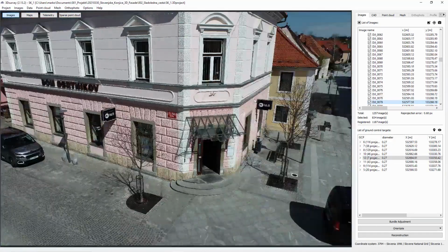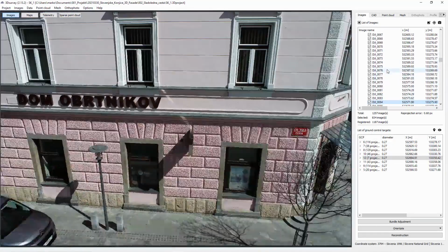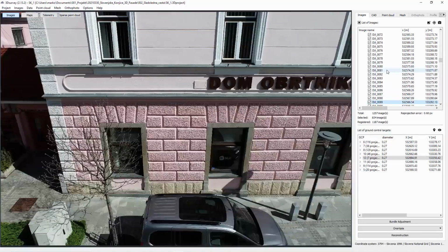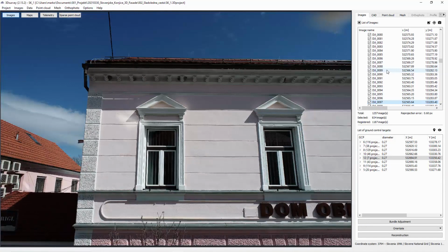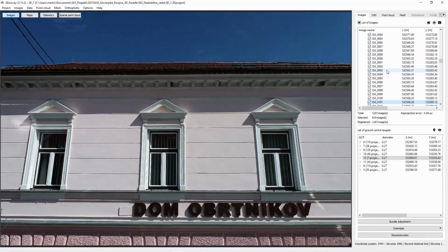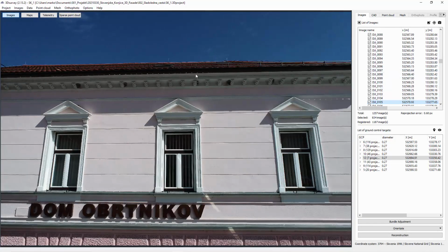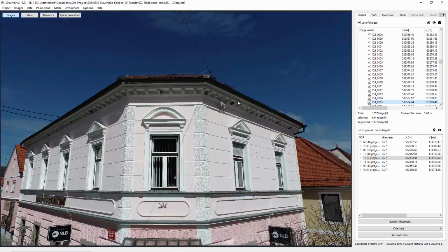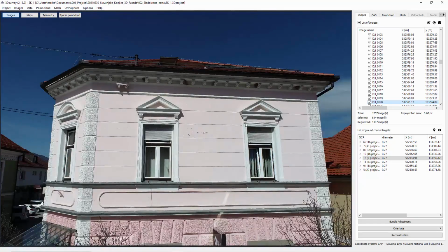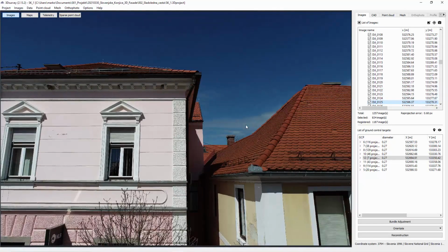And in this way I was just triggering cameras. So right now I'm pretty low, this is probably from 5-meter height. I turn the camera fully up to also get these details right under the roof, which is hard to get from the air, and finish the complete data acquisition for this site.